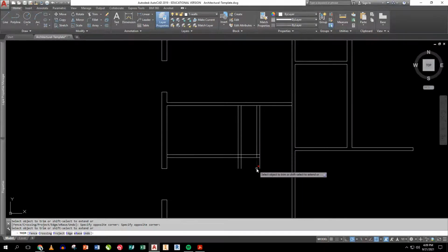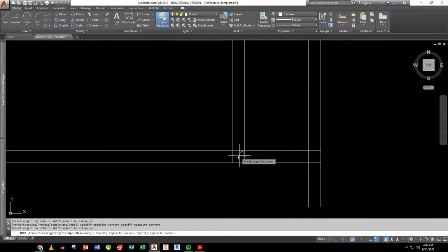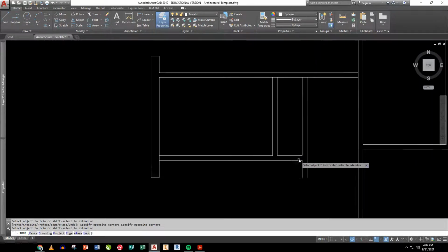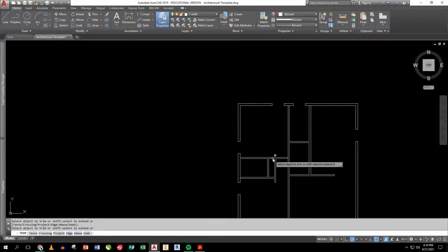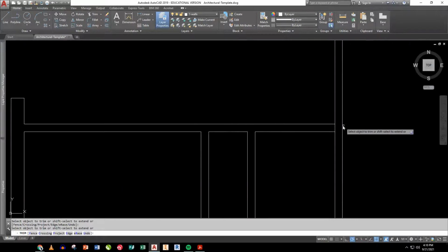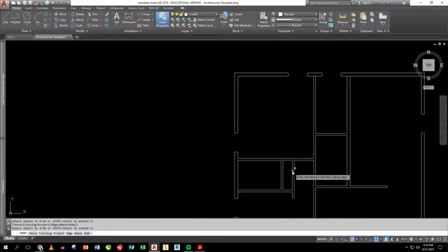That wall actually continues down. This one doesn't. And in fact, it gets trimmed off in here like so, and this stuff needs to be trimmed off here and here, and it needs to be trimmed off there and there. I'm just rolling my mouse wheel to zoom, just in case you've forgotten that. Okay, and I'm pushing my mouse wheel down to pan.